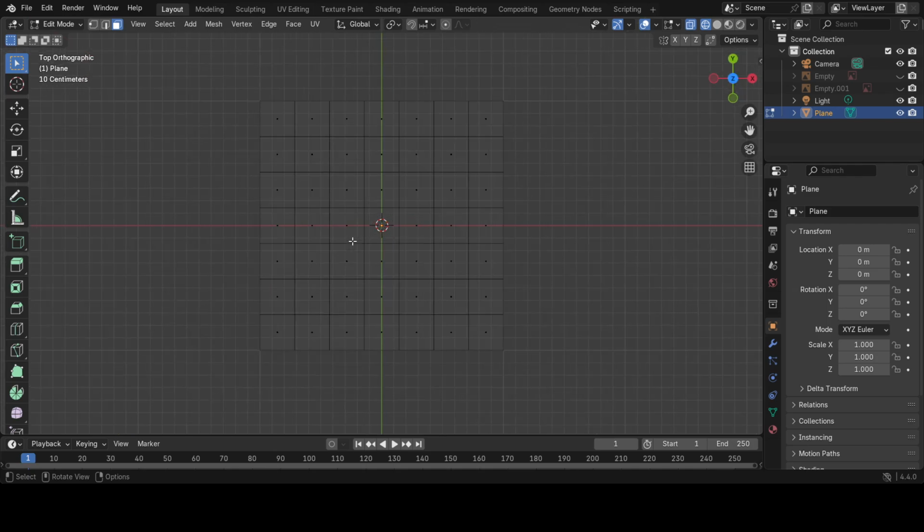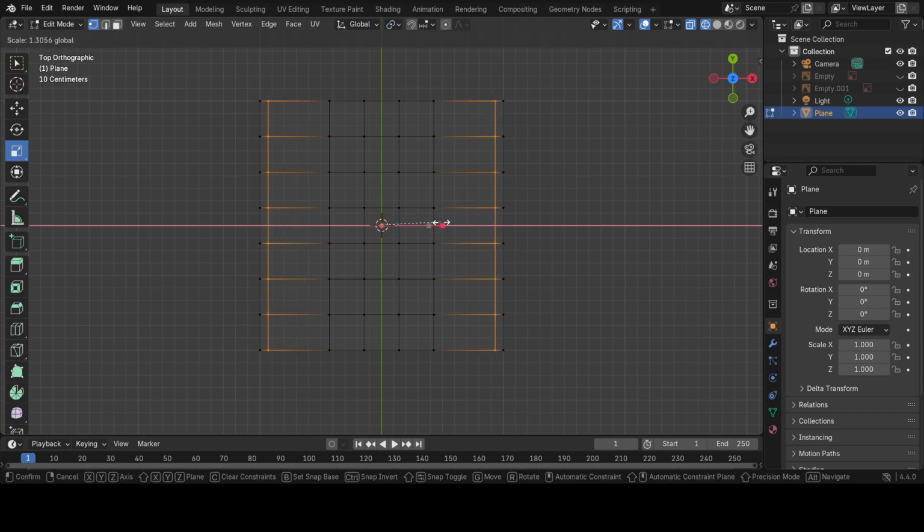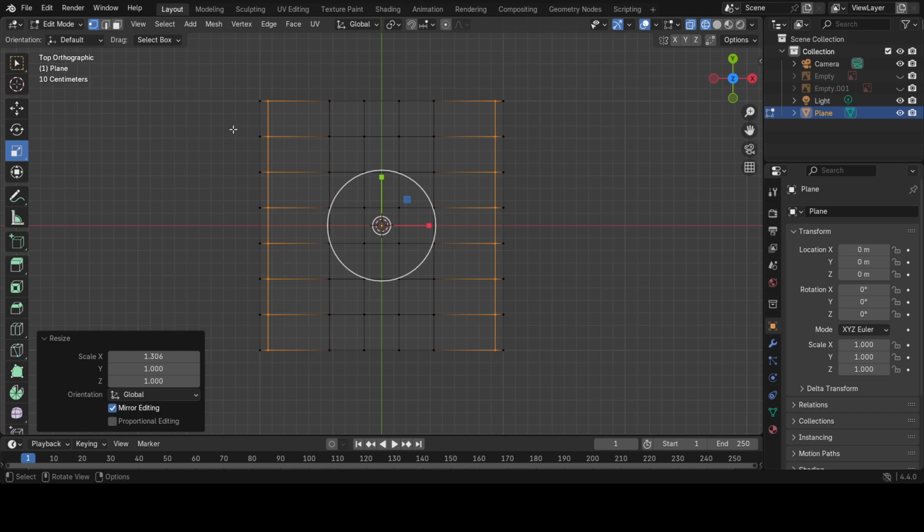top. Now, just like we did with the previous video introduction, where we're building a table, we're going to set it up basically in the same way. So I'm going to start out by hitting the number 1, and then I'm going to select this line of vertices, hold down Shift, this line of vertices, and then go ahead and using the scale tool with the medium point, pull on this so I have an edge. I know that there's going to be like that, so I'm just going to go ahead and do that.